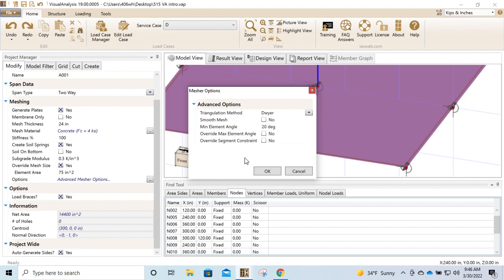I don't think so. So in your case, if you were modeling a footing, we'll get to that at some point, right? You would model this footing, and then you would want to refine the mesh in such a way that you would get convergence of your results. If you were looking for mx, the moment on the x face in local coordinates, you would be refining your mesh and making sure it's getting to some sort of value.